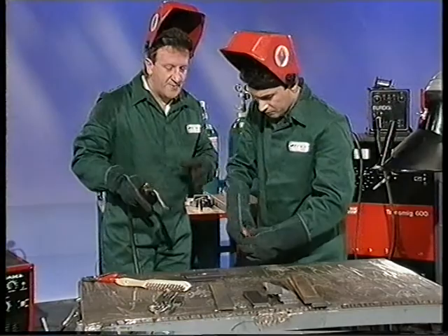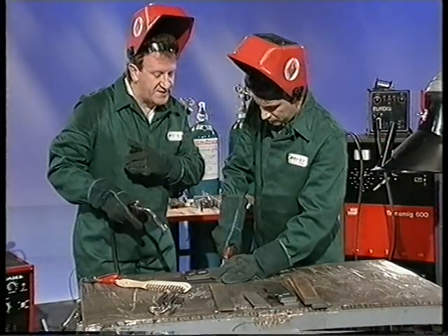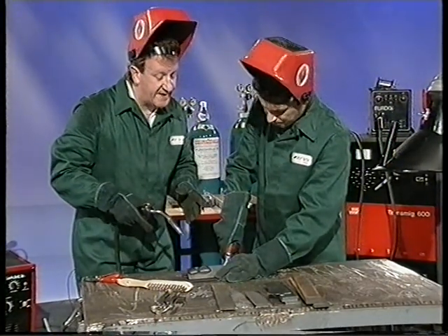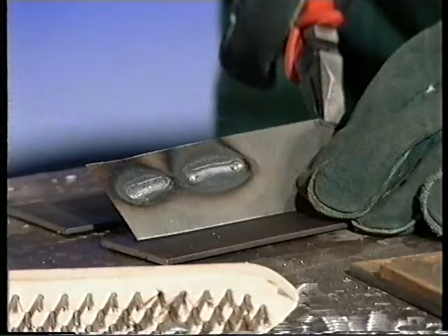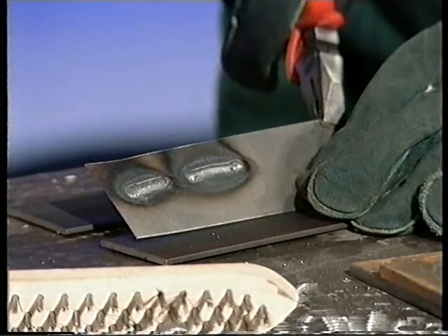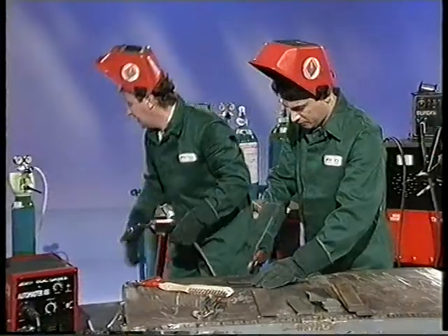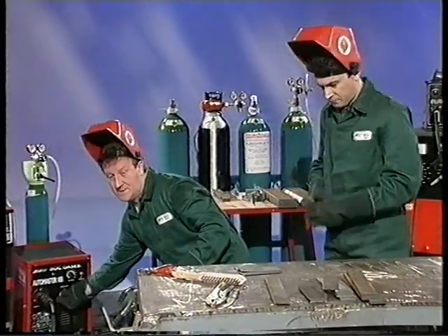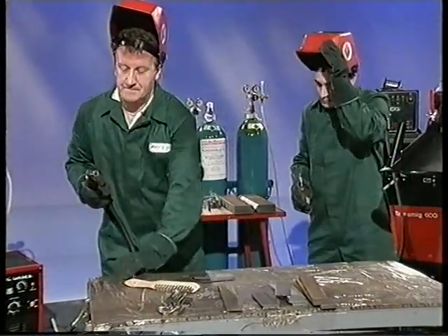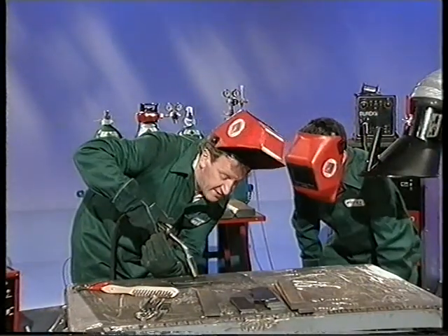Sounds a little more like welding. There's certainly dip transfer taking place there. But in effect now we've got too much wire for the amount of voltage that we've got on. There's not enough volts in that case. The dip was very harsh, and if we continued there'd probably be quite a bit of spatter. Let's give that some more voltage then. Perhaps to there. Try one more little run, mind your eyes.